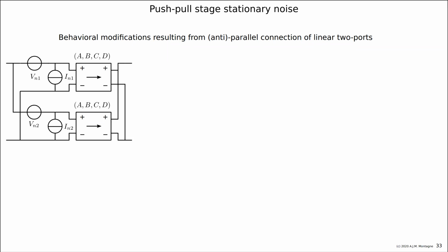But as we did with the differential pair with anti-series connection, we said, no, if we have a series connection, then you can add voltages. That is much more easy. So if we have parallel connection, we can add currents. So we need another model. We need a model in which the noise is represented with 2 current sources. And as you know, hopefully from the previous course, the bachelor course, we have 6 representation methods for noise of 2 ports, for noisy 2 ports.